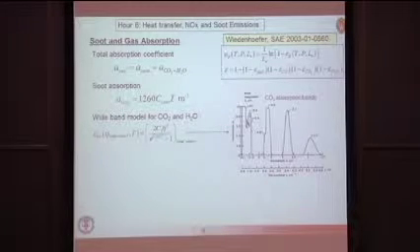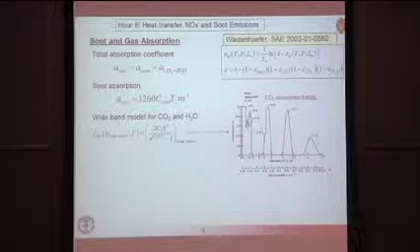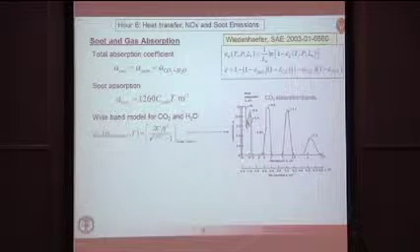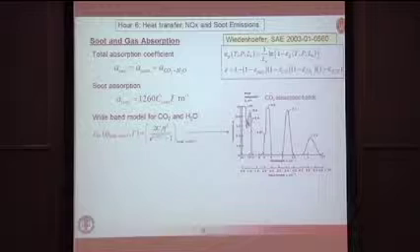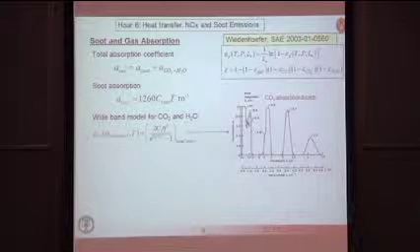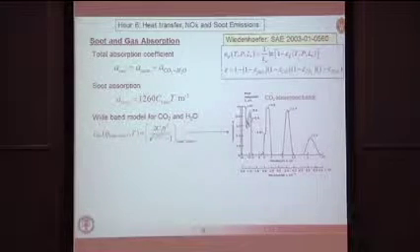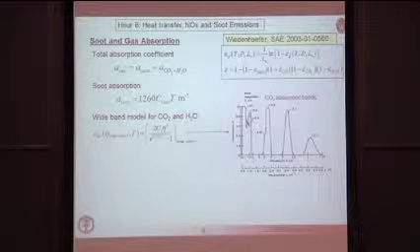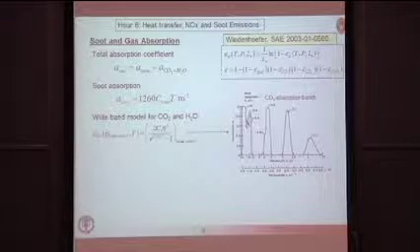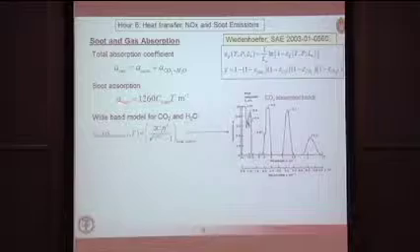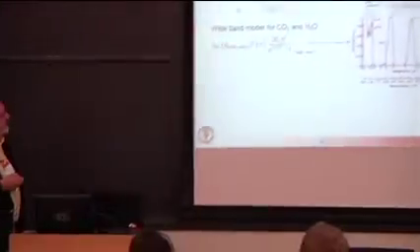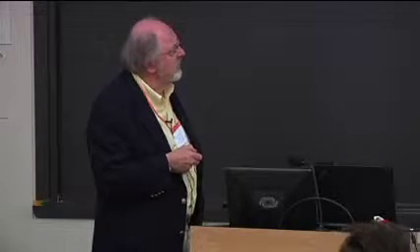You also need the absorption coefficients. So basically, soot is a great absorber. And you also have absorption from gas phase species, notably CO2 and water. But again, we use an expression for the absorption coefficient, which essentially involves a constant times temperature for soot, and then wide band models for CO2, H2O, and those are the main species that are considered.